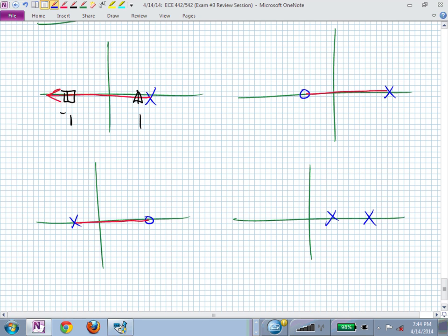Because my asymptotes are guiding me to where my infinite zeros are going. Here, if I just had 2 poles, nothing else, my root locus is going to split those in half. I'm going to come together, they're going to meet right in the middle, and they're going to break away. If you have other poles and zeros anywhere, that half thing is out the window.